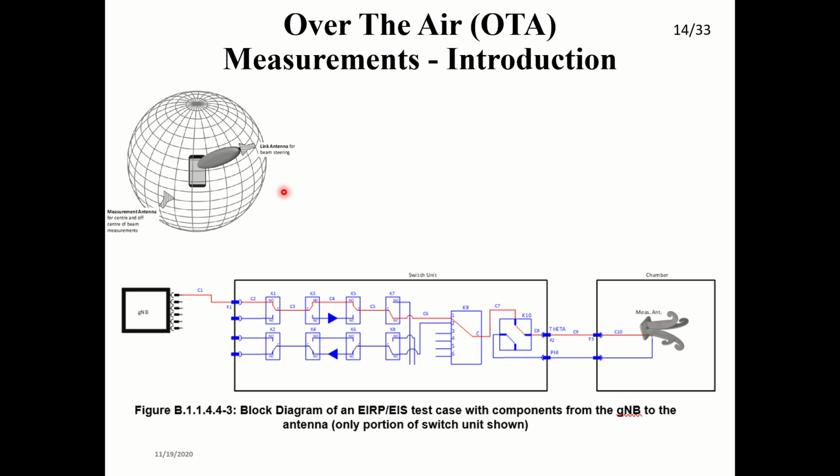Next, in 5G we always use dual polarized antennas, as I covered in 5G OTA beamforming. So how will you test a dual polarized antenna? Conventional test antennas will have dual polarization. You can see here it's a quad ridged antenna. One pair of ridges will be in vertical polarization, another pair of ridges will be in horizontal polarization. So you will have two connections. When you connect this one, it will activate horizontal polarization. When you connect this one, it will activate vertical polarization.